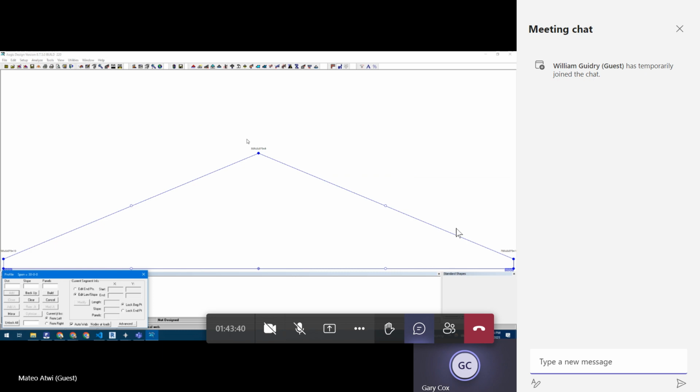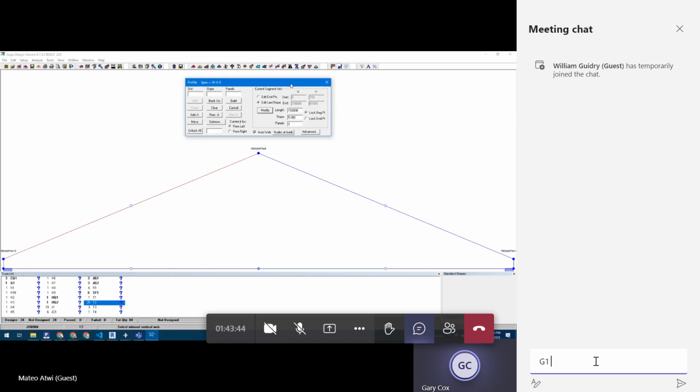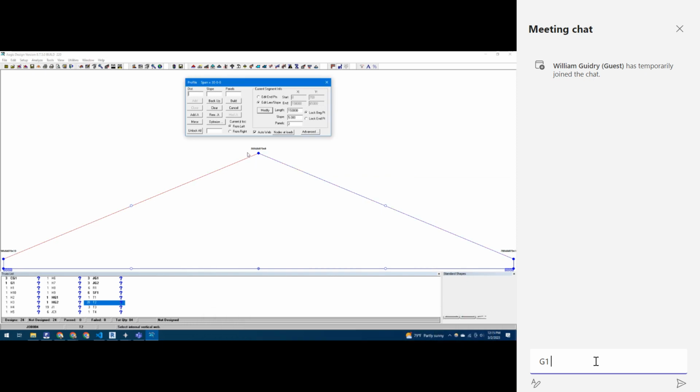I want to show you what tools you have for symmetrical trusses. So wherever you need to add stuff, do it on the left first. Okay. So hit add joint, and then I can mirror it to the other side. Then add it on the bottom. Say anything you wanted to add to the bottom. And then hit mirror. It'll duplicate it on the other side of the truss.